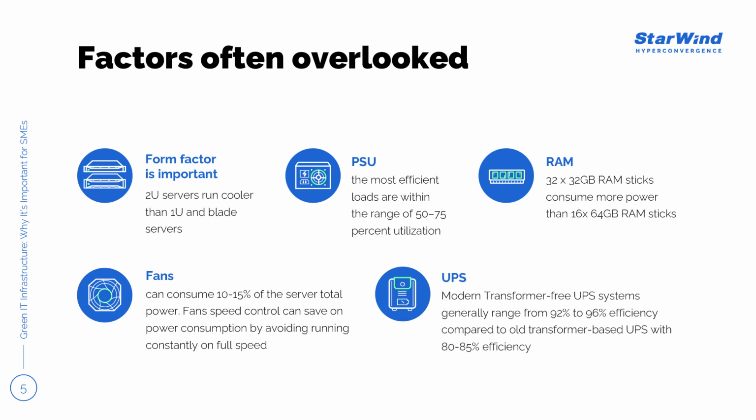Now, the efficiency of a power supply also depends on its load. The most efficient loads are within the range of around 50 to 75% utilization. Power supply efficiency drops below a 50% load, and interestingly, also drops at 100% load, or close to that value, unlike UPSs.